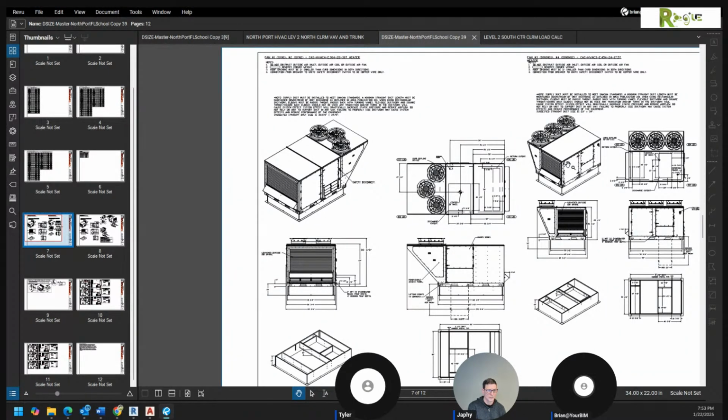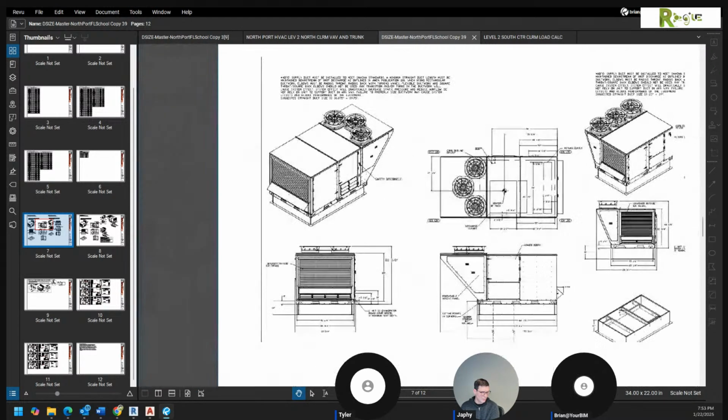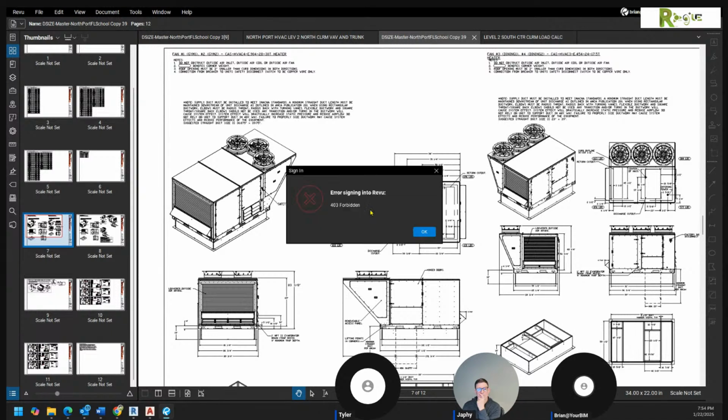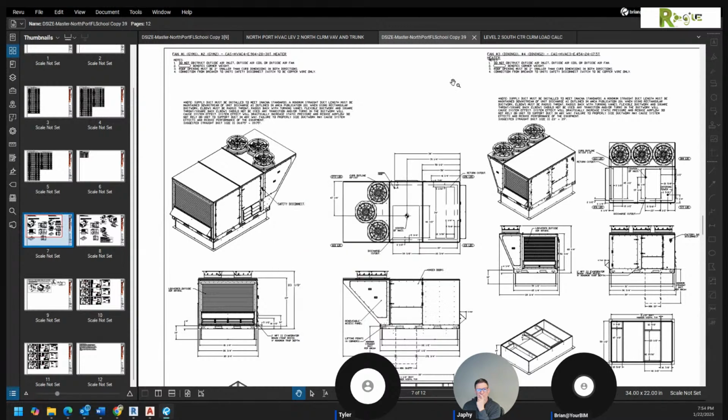And understand, I really could make a bunch of different sizes. I even came up with a way that if you could tell me when the size needed to shift this fan out, which is probably when the width is less than whatever number, I could actually make that go out. They tried to do this as an array when there's no reason to do it as an array. There's absolutely no reason to do it as an array because if the unit got small enough to only have 2 of those, all you would do is turn the visibility of the center guy off, which you could do very simply.